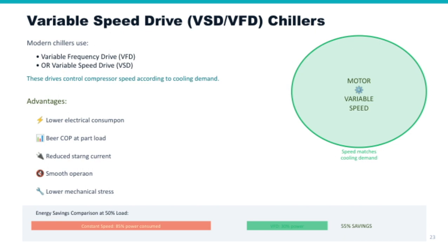But it's not just about energy. These drives reduce mechanical stress, ensure smooth operation, cut down starting current, and improve efficiency at part load. By matching motor speed to cooling demand, modern chillers become smarter, more efficient, and kinder to the electrical system.